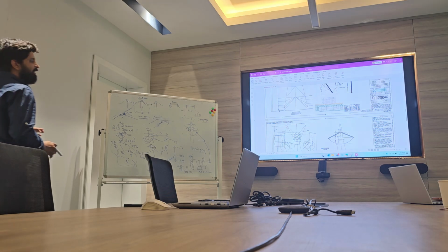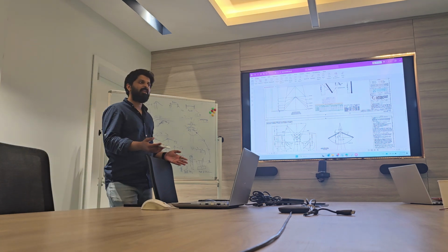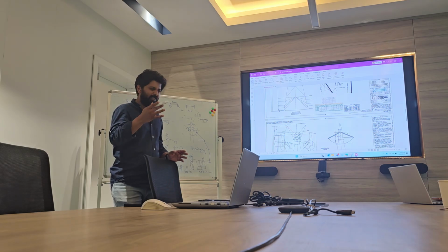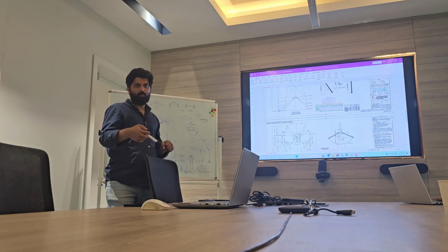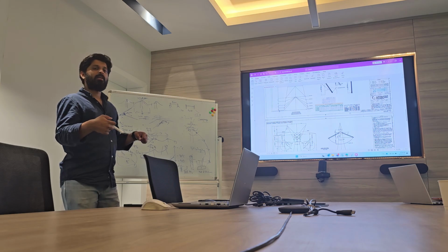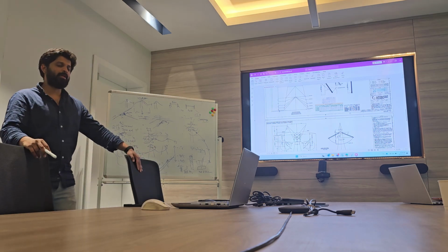Even conductor does not come in rolls of more than 300 meters. Sorry, 5 to 10 kilometer range. Cable comes in smaller lengths, 500 meters. Conductor comes in longer lengths. The exact length of the drum you will check with the supplier.